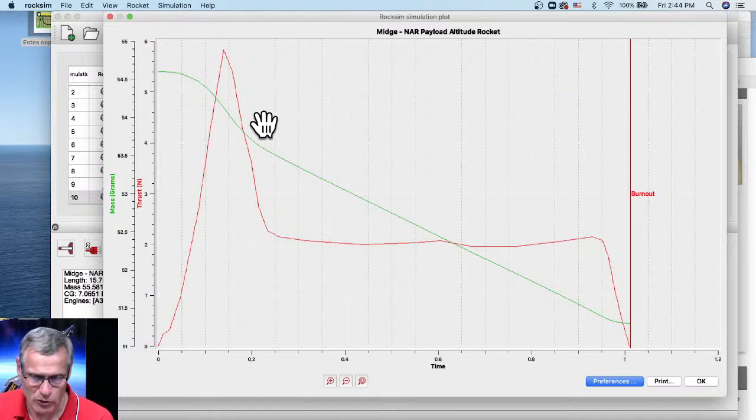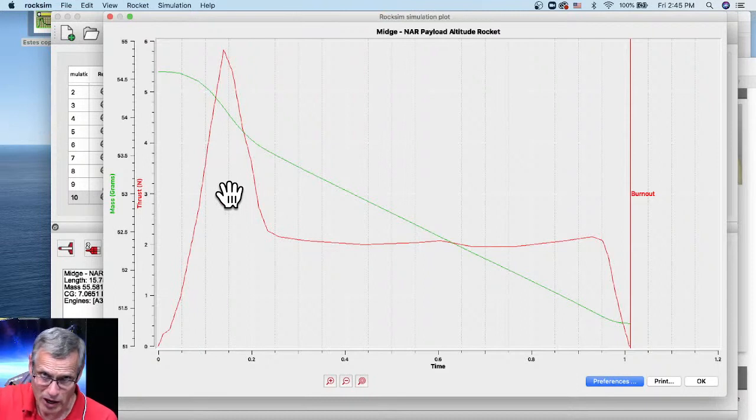It didn't fall off. What I'm looking for is on this green graph right here. At 0.1 seconds, which would be right here, I should see a 5-gram drop in mass, going from about 54 down to under 50 grams when that pod drops off. It didn't drop off. So I'm thinking, why didn't it drop off? Because I forgot to tell it to drop the pod off.